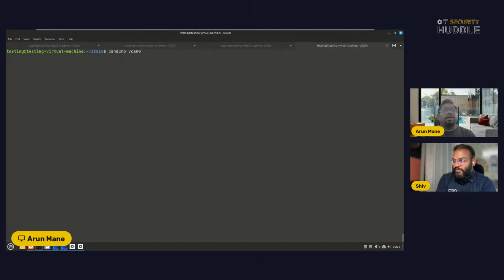That is two ways to put it into the answer. Actually, it depends on the developer, because they know how to calculate the entire errors, and based on that they can rectify. Otherwise, if they do not mitigate that, it turns into a bus-off attack. The entire bus, the two-wire communication, goes down in that case. So it's called a bus-off attack.